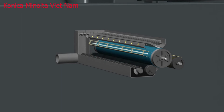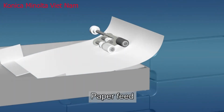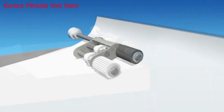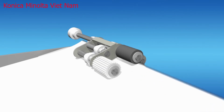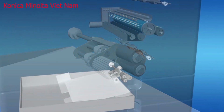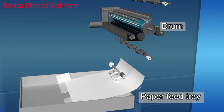In synchronization with the start of image formation on the drum, copy paper is sent from the feed tray with perfect timing. At the paper feed unit, several rollers with different functions work skillfully together to send single sheets of paper to the drum surface. Furthermore, the control board conducts precise control of paper feed speed and timing in order to ensure a perfect match for the paper edge and the edge of the image formed on the drum.